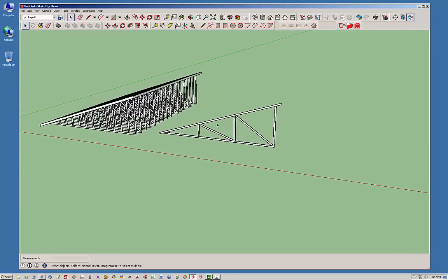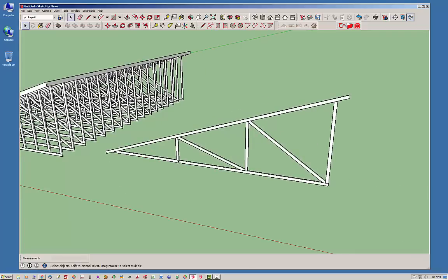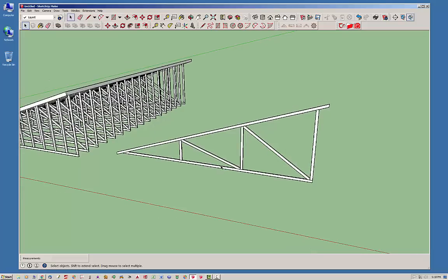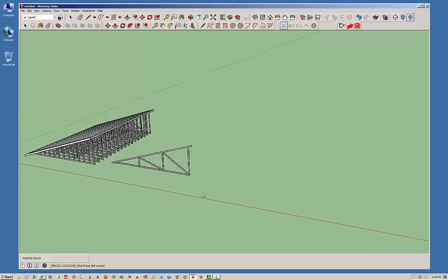Basically, the larger the truss is, the more internal webbing you're going to require, because the length of this panel can only get to be so long before this member gets too long for its size, and therefore in bending and lateral buckling and that sort of thing, it's going to have issues. So that's why as you get a larger and larger truss, you end up having to use more webs.